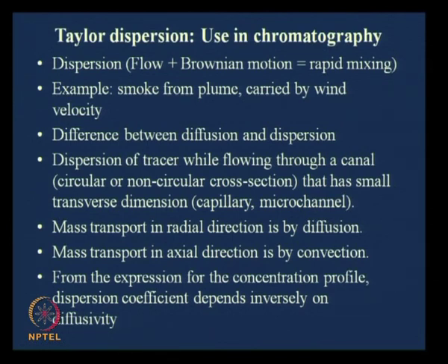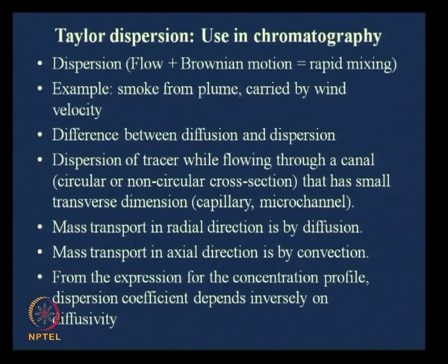Microchannels are pretty much non-circular. If you see how the etching is done, we expect that there would be an aspect ratio and there would be an angle, because that is how the etching takes place. So, you will end up with a non-circular cross section. Now, this Taylor dispersion is important when you have a small transverse dimension, that means either a capillary or a microchannel.